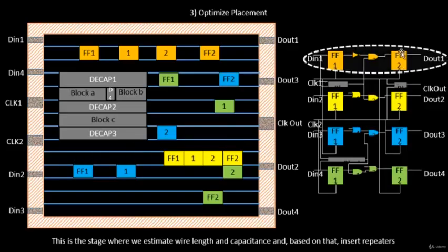We'll start with the first stage. The first stage is flip-flop 1, which is close to D in 1, and flip-flop 2 is close to D out 1. Assuming there is a person sitting over here and a listener sitting over here, this is the sender and this is the receiver. So this port sends some signal, and it has to cross a distance which is quite decent. Whatever this sender sends, flip-flop 1 is able to receive without any deterioration. So signal integrity is maintained between the input port and the flip-flop 1 input pin.